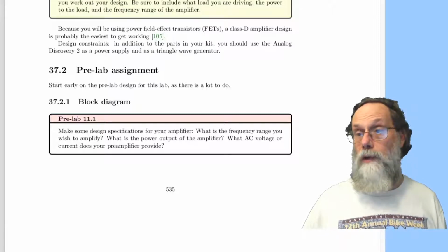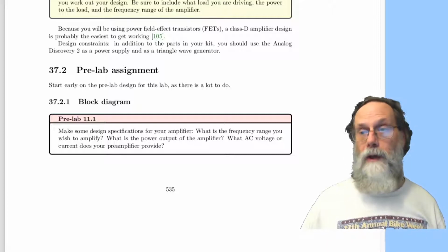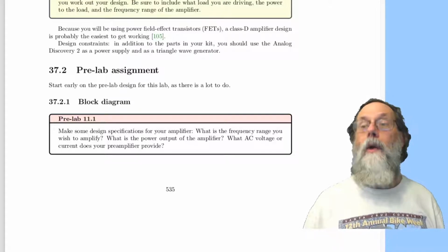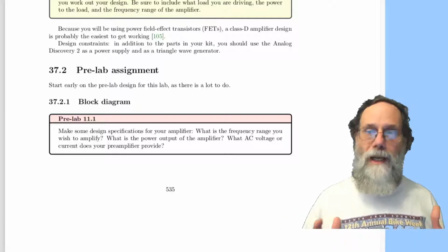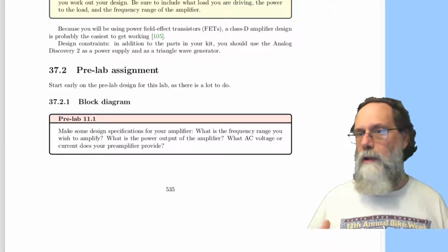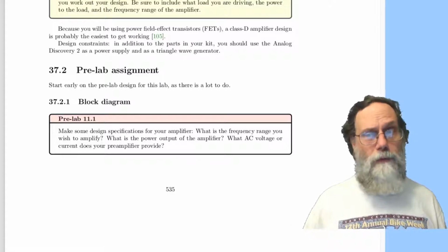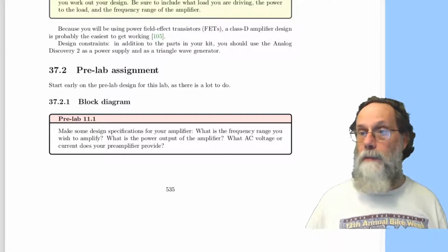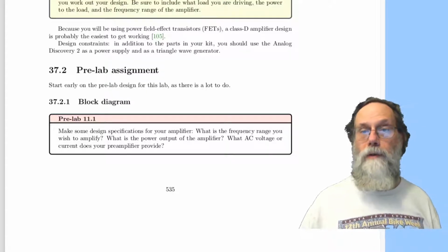So what frequency range do you want to amplify? Are you trying to amplify something for a voice range, or are you trying to amplify something for a music range? Generally, when people are doing voice, they use a much narrower bandwidth than when they're trying to do music. And for voice, you tend to emphasize the part that carries the information in speech. So 200 hertz to 5 kilohertz is often plenty for speech. But that's not very good for music. You'll lose the bass, you'll lose a lot of the timbre that comes from the higher harmonics. So depending what your goals are, you have to figure out your frequency range.